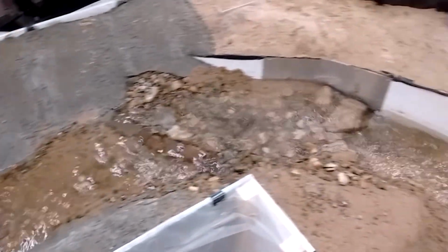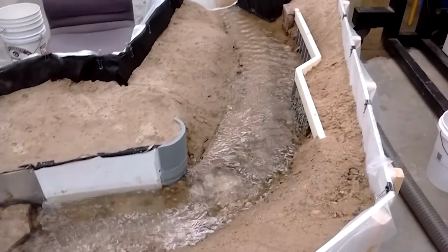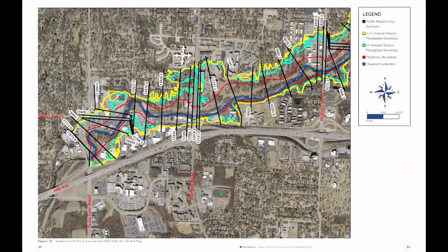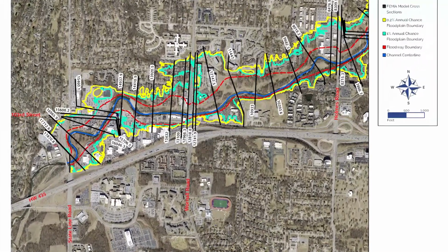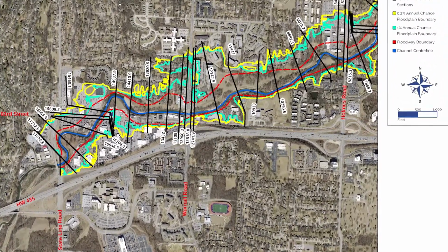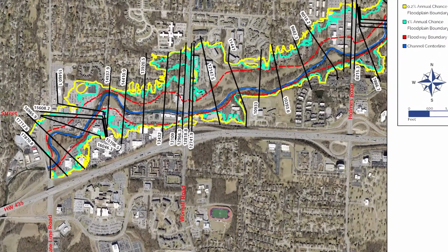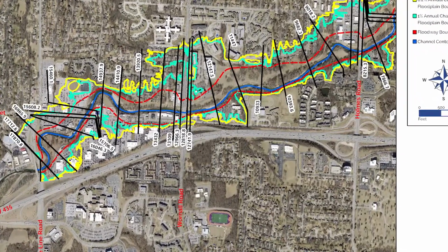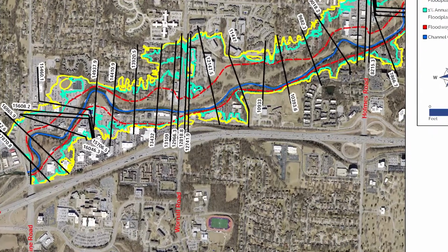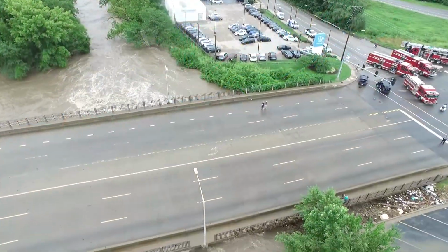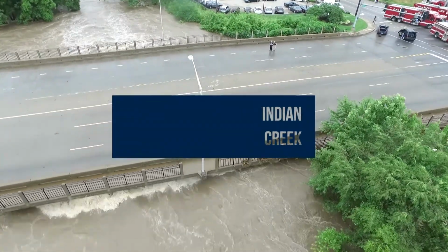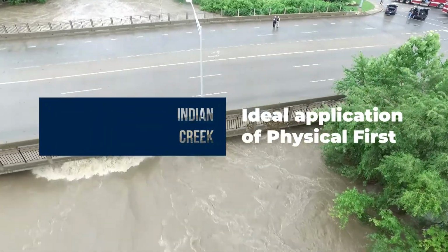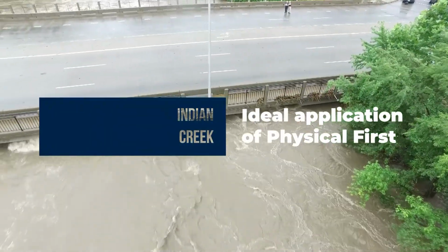So for this August event in question, there were several questions that were raised about the hydraulic models that existed for the creek at that time. And one of those is they did not seem to indicate the flood extents accurately. There were also questions about, since the existing models were one-dimensional numerical models, there was not a lot of information about flow patterns and how the water actually ended up where it was physically observed later on.